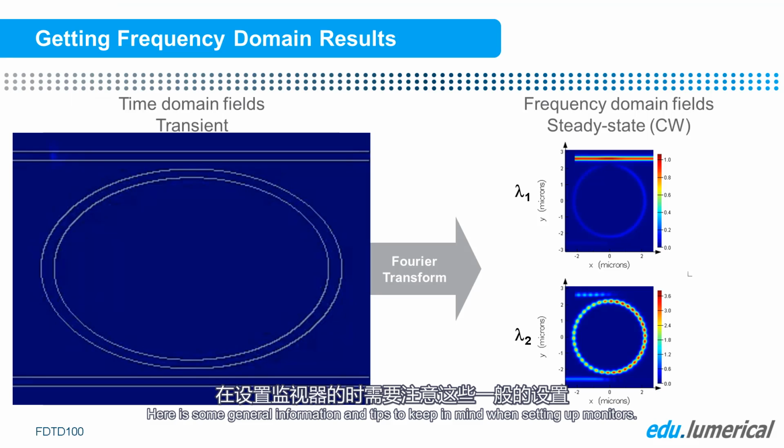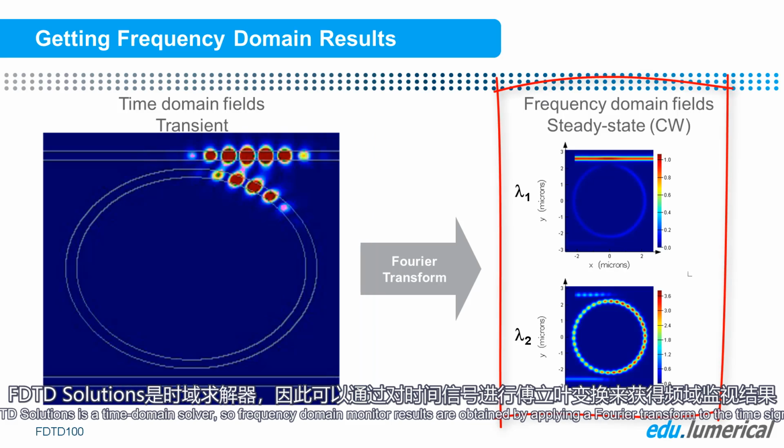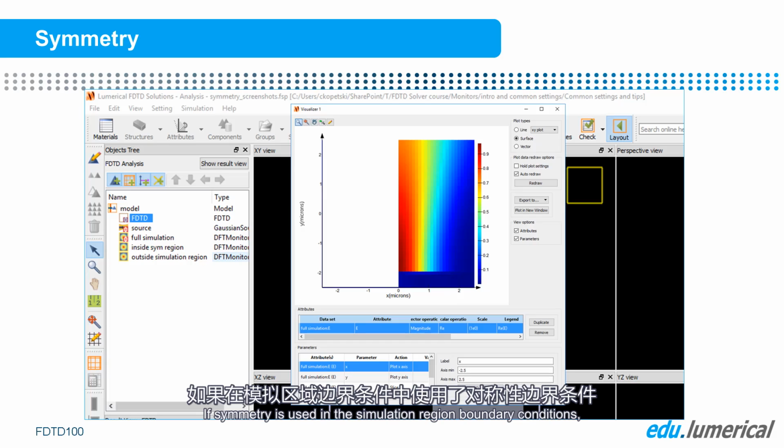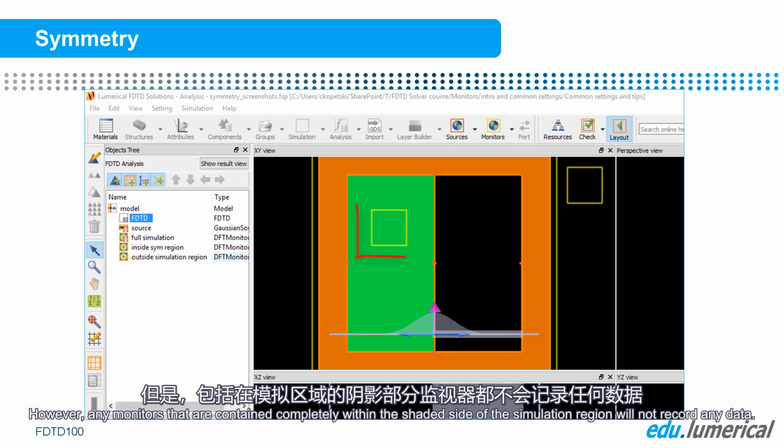Here is some general information and tips to keep in mind when setting up monitors. FDTD Solutions is the time domain solver, so frequency domain monitor results are obtained by applying a Fourier transform to the time signal. To review the details, see the FDTD algorithm section of the course. If symmetry is used in the simulation region boundary conditions, monitor data will be unfolded according to the specified symmetry to give the full field profile. However, any monitors that are contained completely within the shaded side of the simulation region will not record any data.